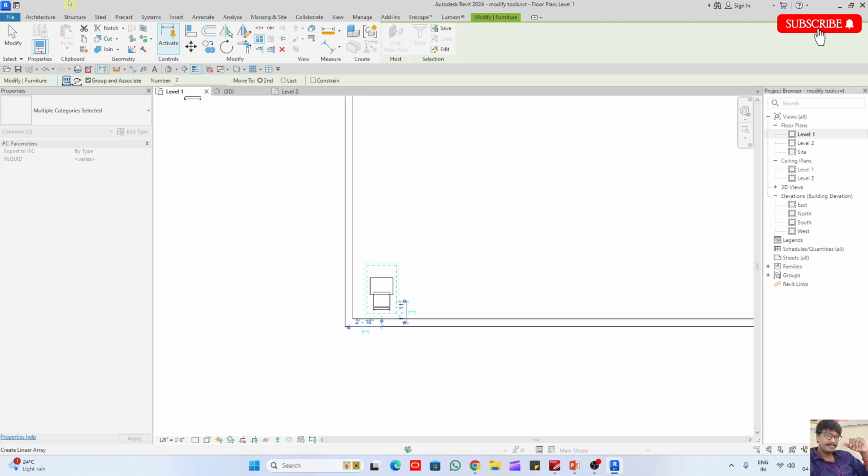If you want that behavior in Revit, what do we have to do? Separately we have an option called groups. When we array, that object behaves like a group. For example, we made it like this. After the array, I don't want that chair, I want some other chair. It's a group, so you can go inside the group and change it. All the array will be changed. So this set behaves like a group and